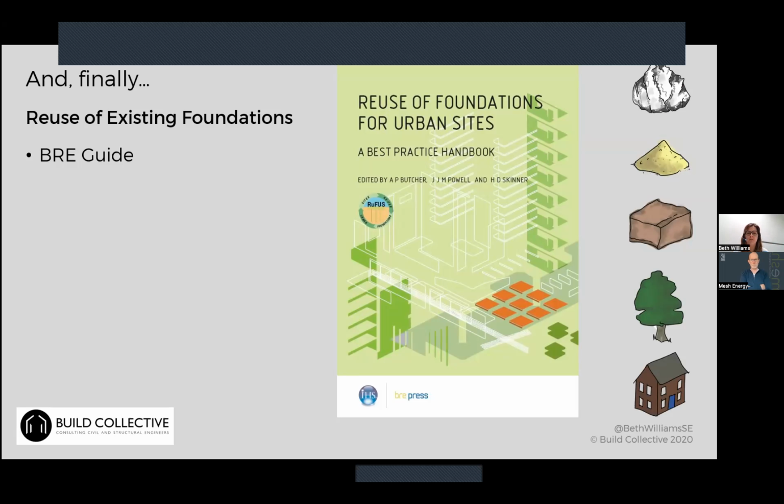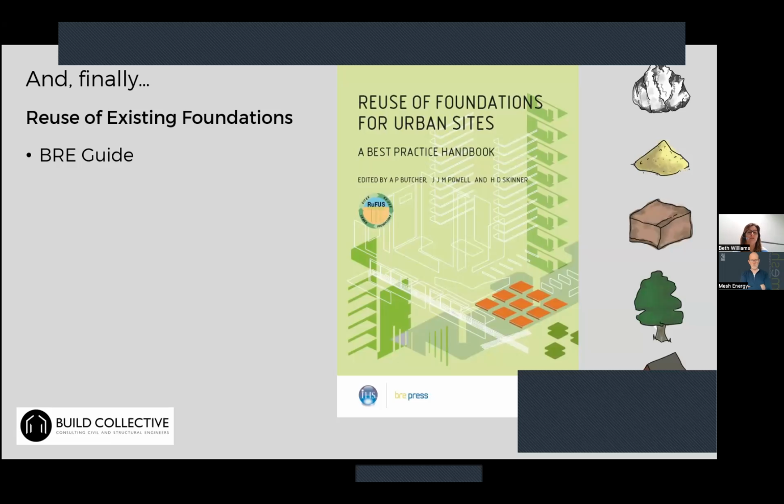That's particularly true for strip foundations, because you might then end up needing to underpin or widen the foundations locally, or just replace them locally with a new foundation. So if you want to use them as they are and not edit them too much, you want to keep the loading profile similar to your original structure.